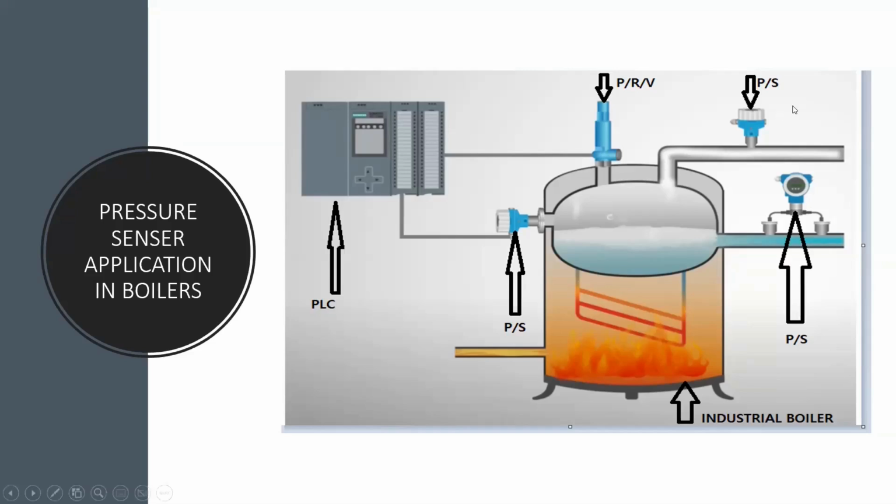We also, like in the case of the third sensor shown here, can checkmate the volume of steam sent to the destination machine. Assuming the boiler is having about 8 bar, and the destination machine requirement could be, we say, 5 bar or even 4 bar. For example, if it is 4 or 5 bar, then with the help of this pressure sensor, we can now say to the pressure sensor, open.